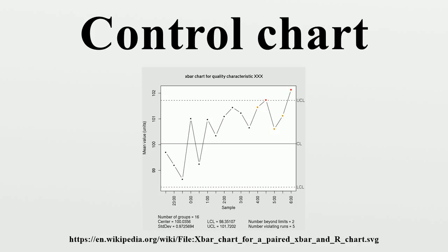The purpose in adding warning limits or subdividing the control chart into zones is to provide early notification if something is amiss, instead of immediately launching a process improvement effort to determine whether special causes are present. The quality engineer may temporarily increase the rate at which samples are taken from the process output until it's clear that the process is truly in control.